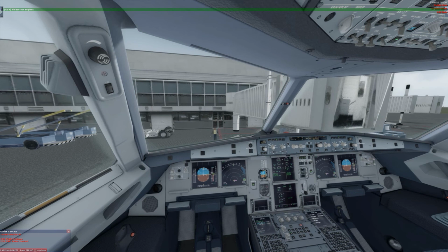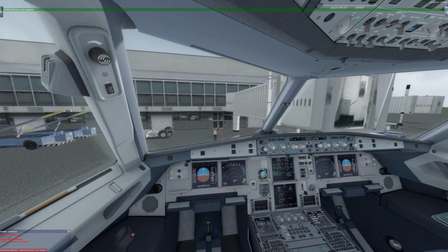Parking brake set. APU pressed. Engine anti-ice 1, 2 off. Navigation lights turned off. Runway turnoff lights off. Seatbelt signs switched off. Fuel, all fuel pumps off. APU airblade switched on. Strobe lights selected off. Shutting down the engine 1. Engine 2 shut down. Shut down flow complete.